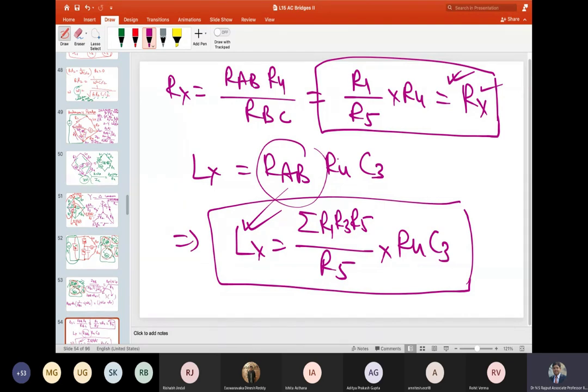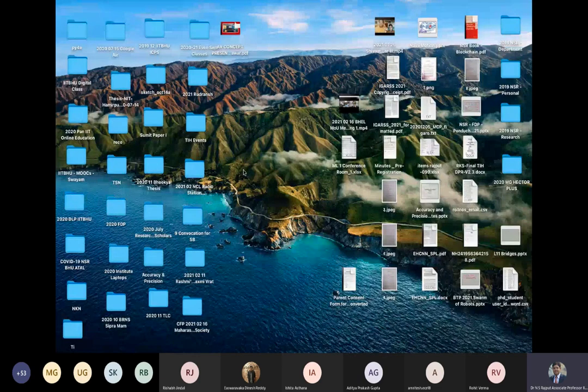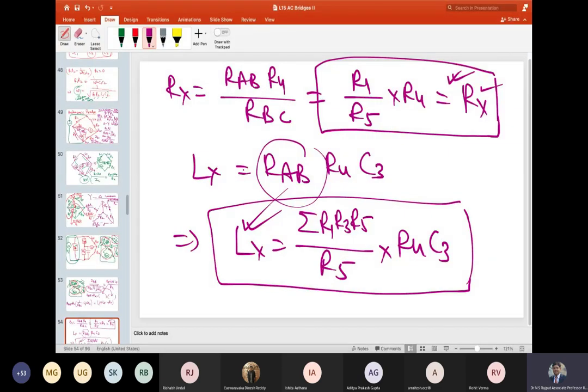And I understand that all of these bridges were more or less similar to the standard analysis of arms of a Wheatstone bridge. So all you need is to obtain the equation for balance condition. Usually prefer to have the ratios of resistive versus impedance components so that they cancel each other and create equivalent real and imaginary components which you can compare conveniently, right?